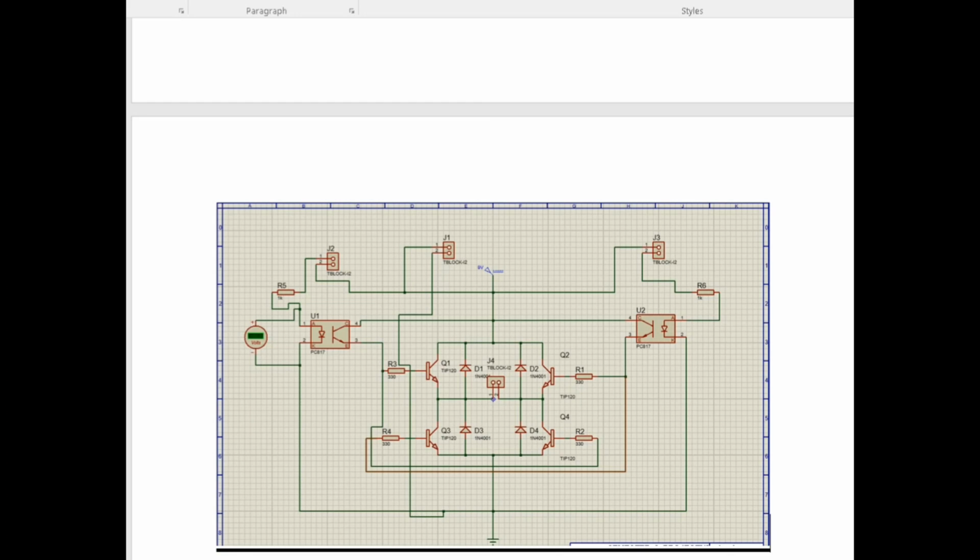R1 is connected with R4, and R1 and R4 are connected with U2. Similarly is the case with U1. U1 and U2 are attached with R5 and R6 respectively. Further, they are attached to the switches where you can control the movement of the motor, and they are attached with a 9 volt voltage source, J1, which is the voltage source that is being provided.